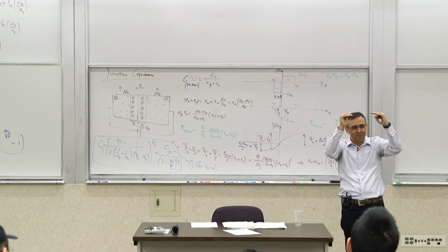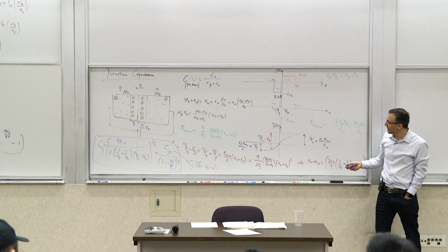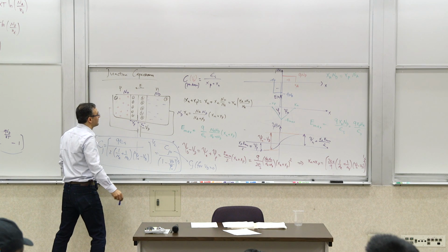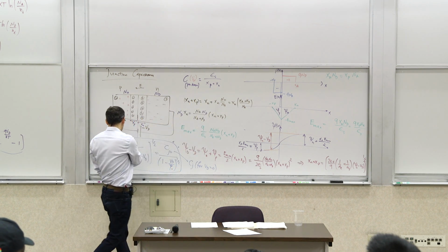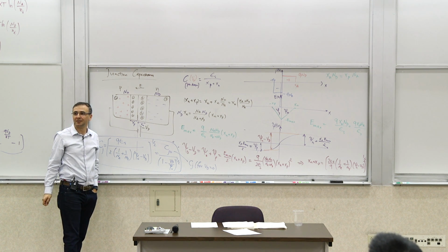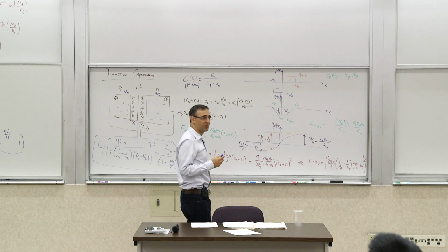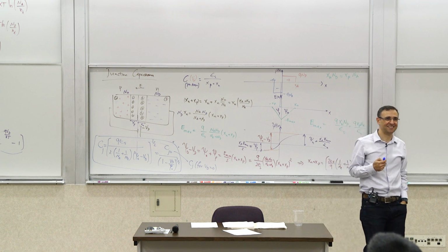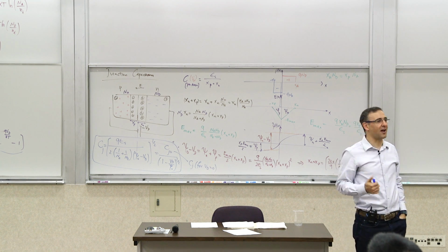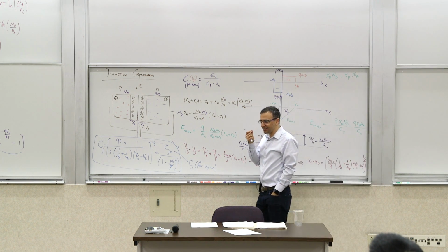And you push it up, up, up. Now what happens, so that's fine. So we make the depletion region smaller. But if you make the width of the depletion region smaller, what happens to your capacitance? You can see it more easily here, but you can also see it from Na and Nd. What would happen to your capacitance per unit area? It goes up. Now, is it a good thing if you have a lot more capacitance in your device? Or a bad thing? It depends on what you're trying to do. But if you're trying to make an amplifier that operates at higher frequencies, we'll see that that capacitance is not a good thing. So what do you need to do?